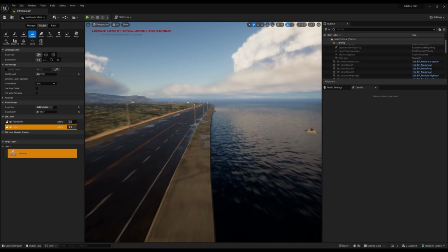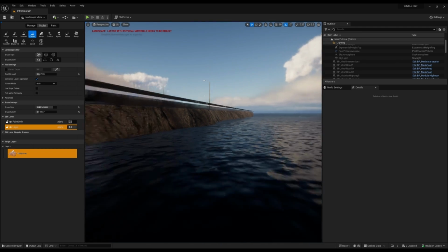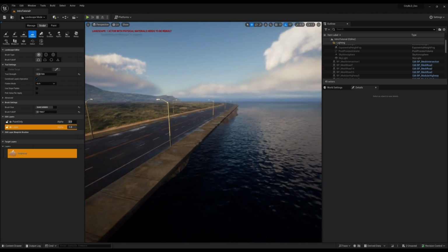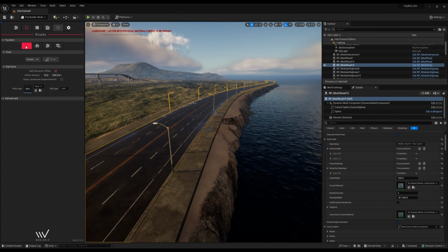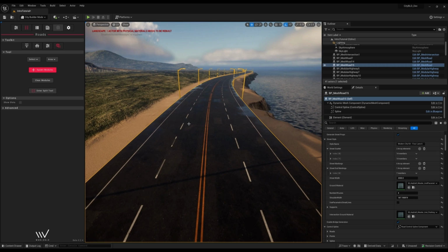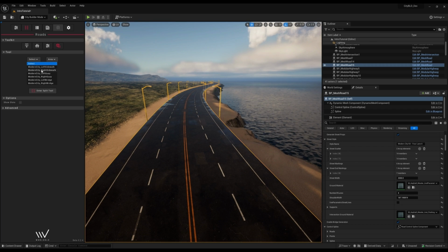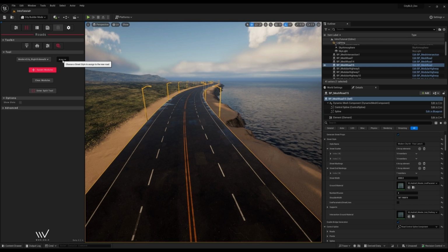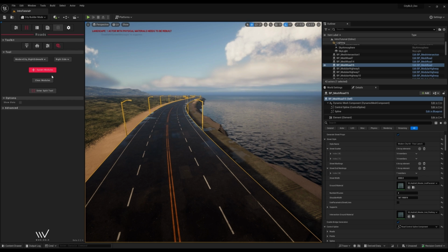Now you'll notice a new issue. The road has no edge. We need to add an additional wall to this side of the road. We can do that by linking a road module to the right hand side here. Let's switch over to the road modules tab and clear the old modules out. The sidewalks are both modules, so this operation removes them. Here we need to choose the right facing sidewalk module and add it in manually on the right hand edge.